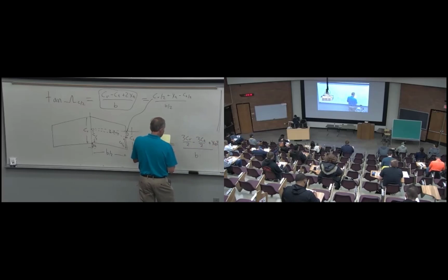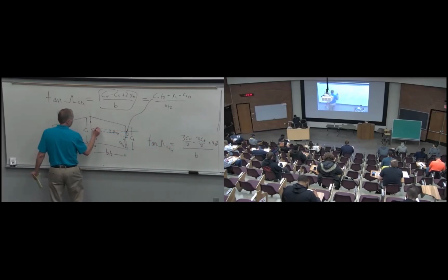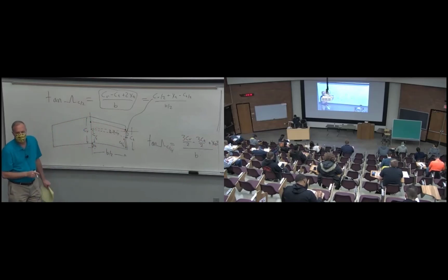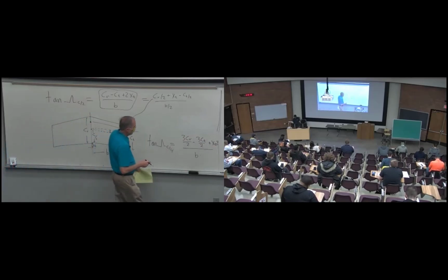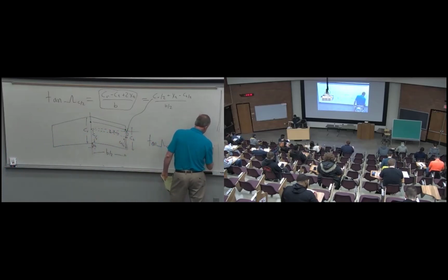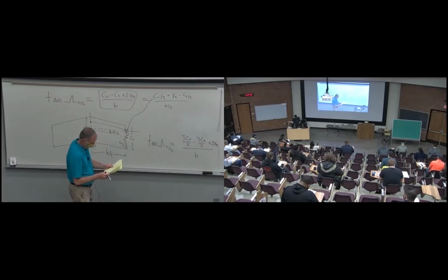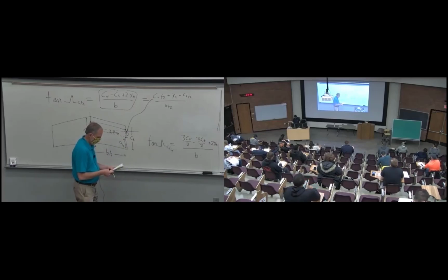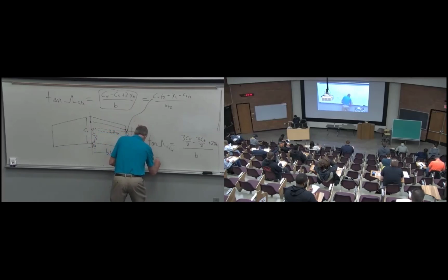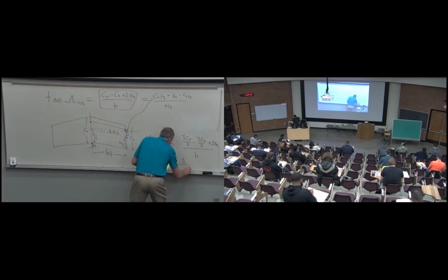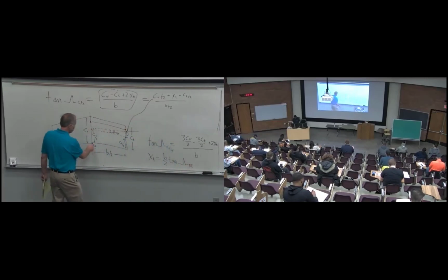Double checking my formula here. Yeah, so if you need the quarter chord, which means you're only going 1/4 of the way back, and you want the angle of that line, that's the formula for that. That's xt times 2. So I guess we could write it like that to make it clear. Oh, and while I'm giving you formulas, this xt distance can be calculated if you know the trailing edge sweep, although you can also calculate it from other geometry. So if you ever need the trailing edge sweep angle and you know xt and b, you can calculate it from that.